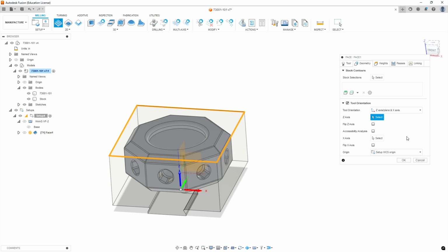in the neutral position. So this part sits on a C-axis and an A-axis, and the C is in orientation with the primary spindle. We pick that plane of the top face, and then X is going to be an edge. It's horizontal. That's pointing to the right, and that's our other rotating axis. What rotates about X is the A-axis.